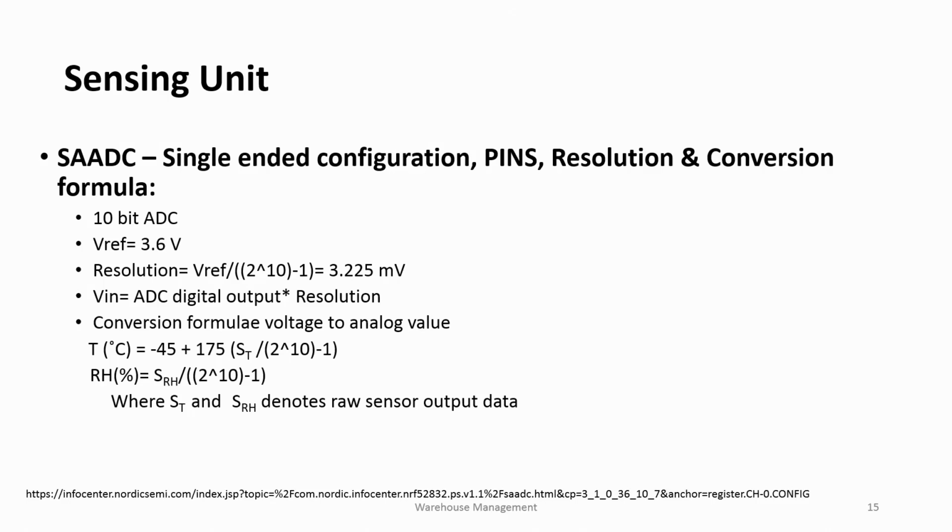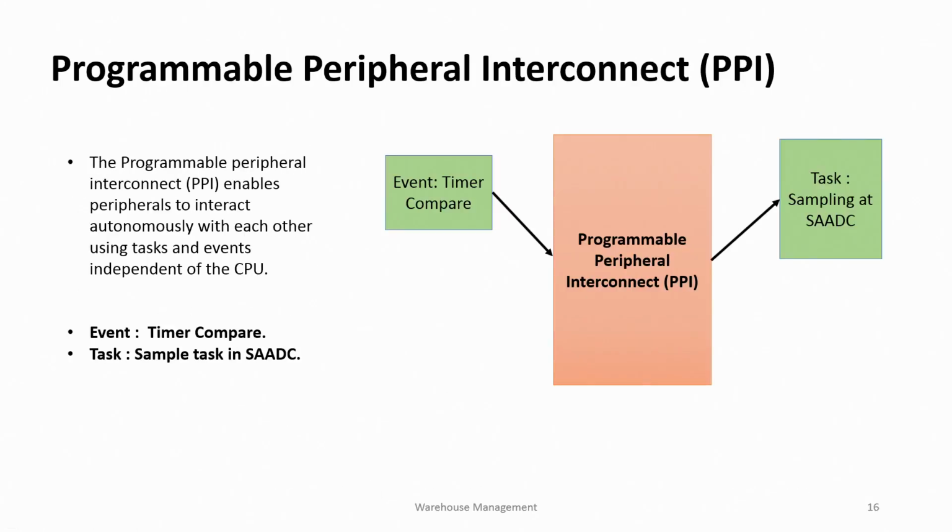Do not ever hesitate to look up the data sheet of the system. It will tell you what it corresponds to as far as temperature is concerned. If you read a voltage, how do you substitute and how do you convert, that is given here, right, this expression. It is not our expression, it is from the manufacturer. Similarly relative humidity, there is an expression for it, you can choose this expression, and then